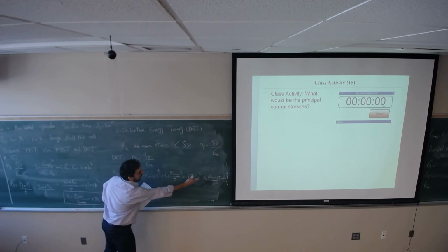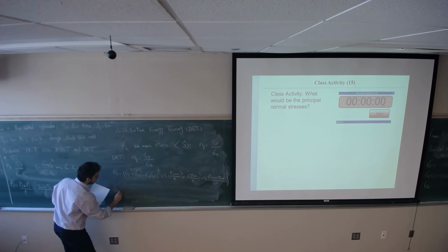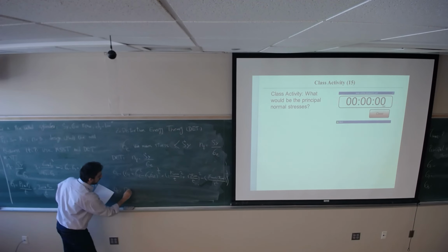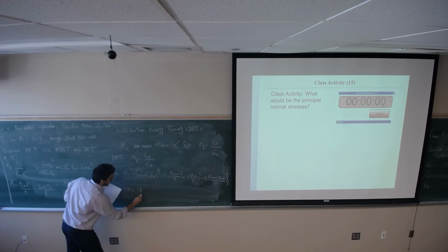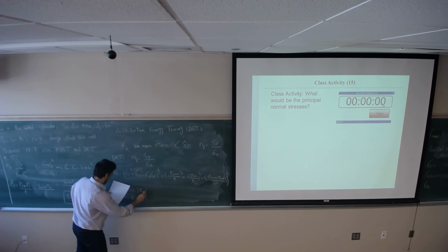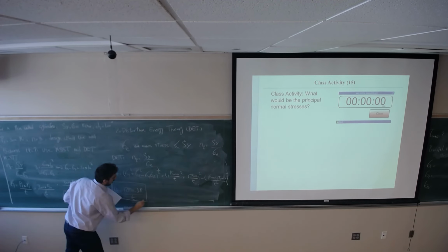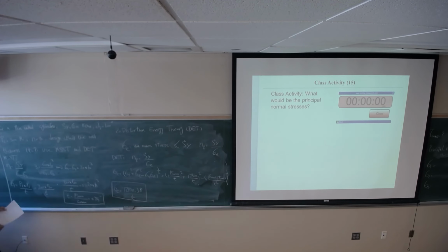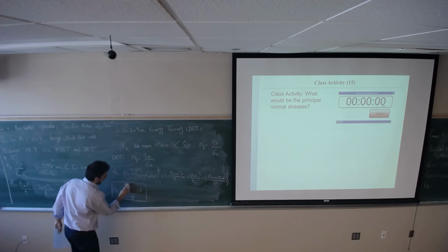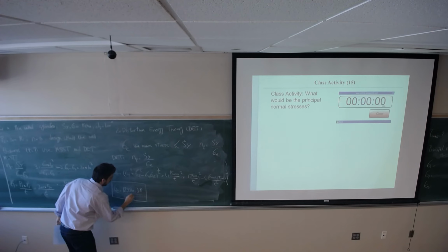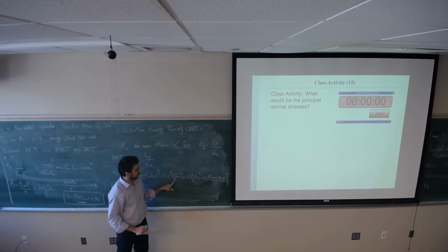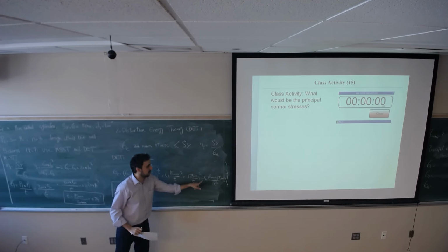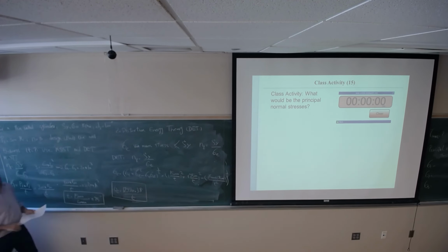If you add them up, you will find sigma von Mises equals 12,990.38 divided by t. This squared divided by t squared, minus this divided by t squared, the summation square root.